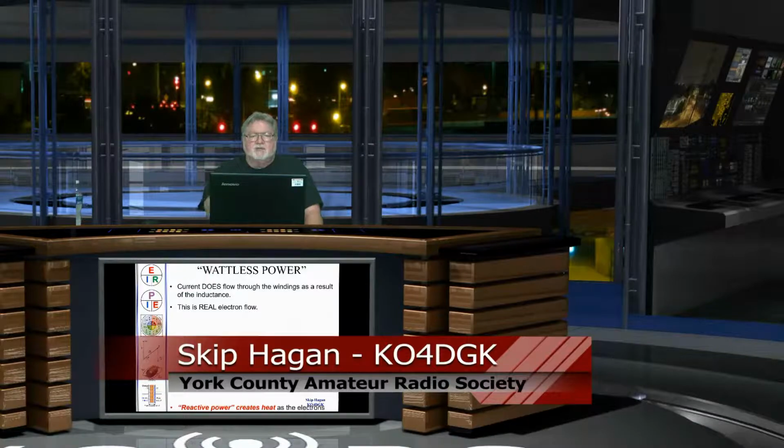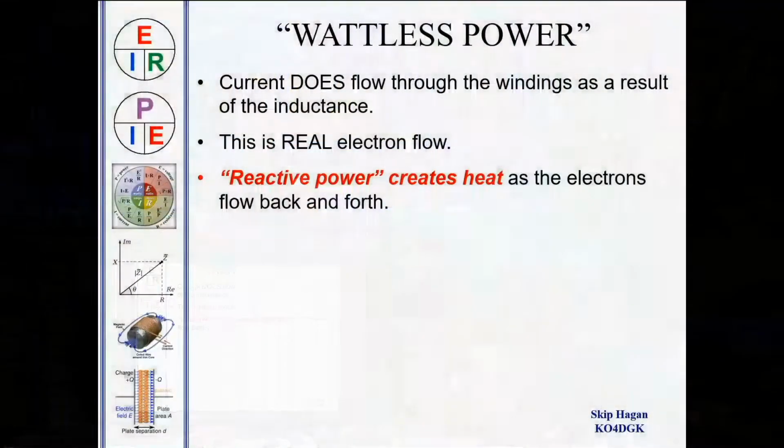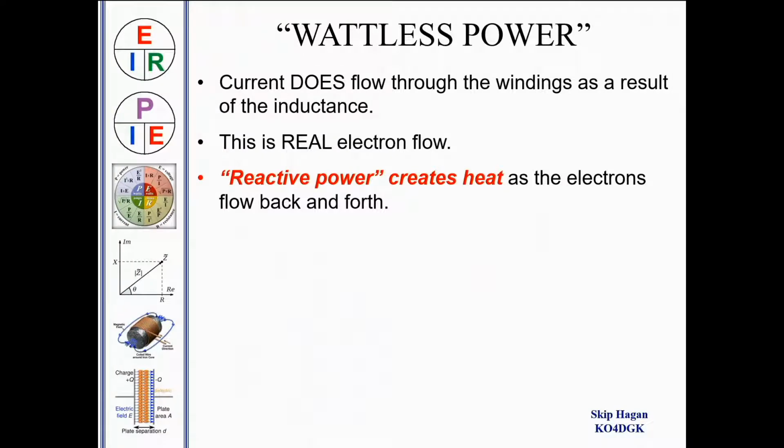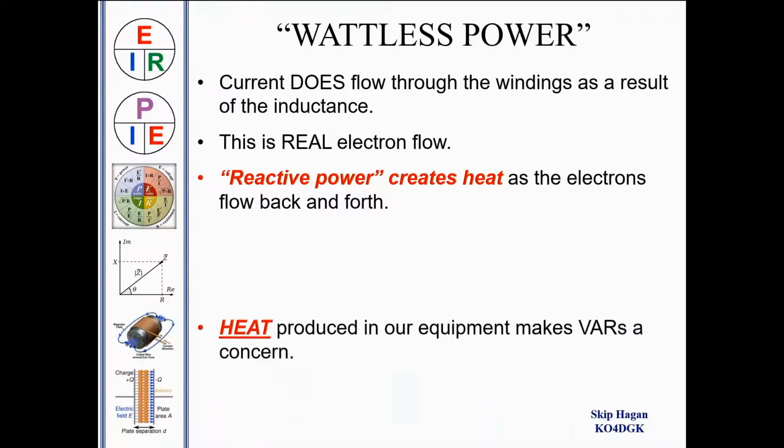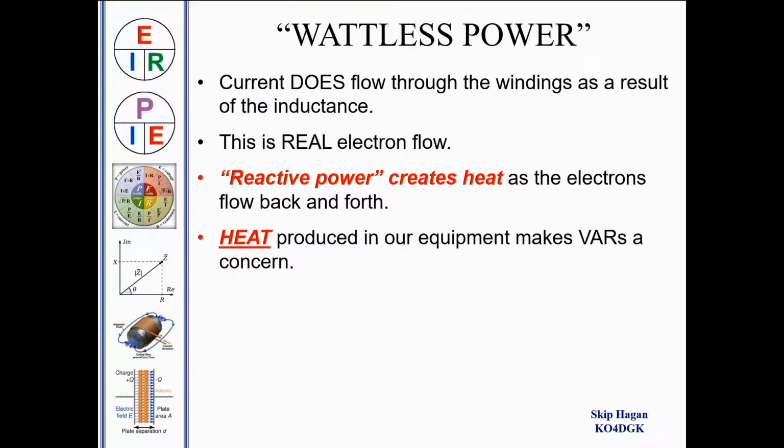And because it is real electron flow, reactive power creates heat. That electron flow back and forth, even though it's coming in and going out and doesn't do any work, we still have electron flow and we get heat. The heat that's produced through reactive power is just as real as the heat that is produced from active power.